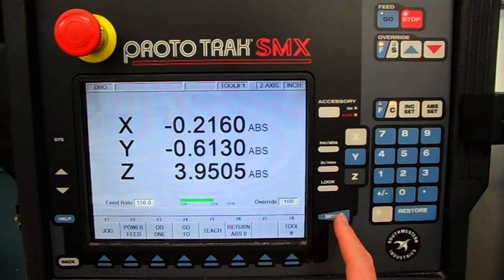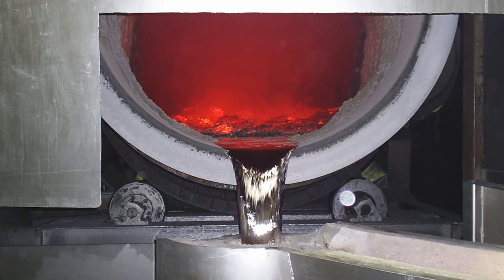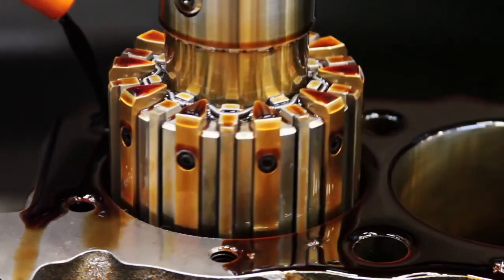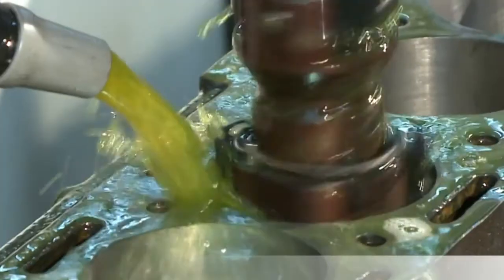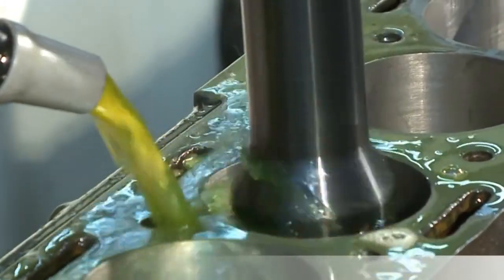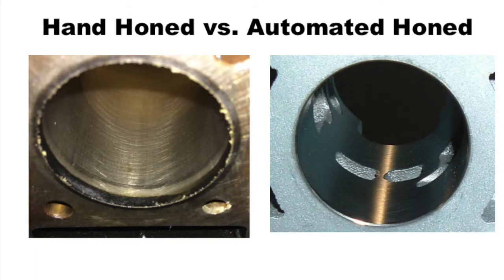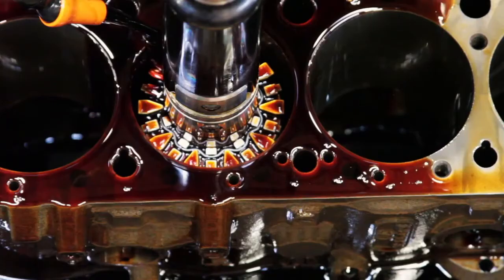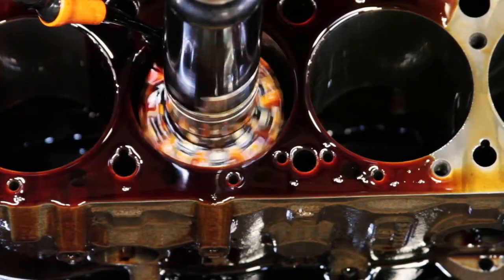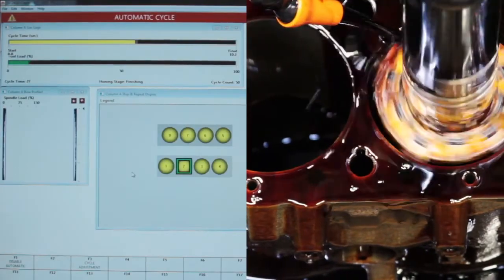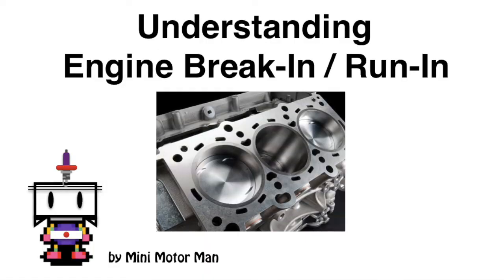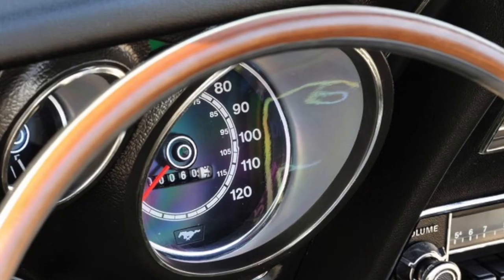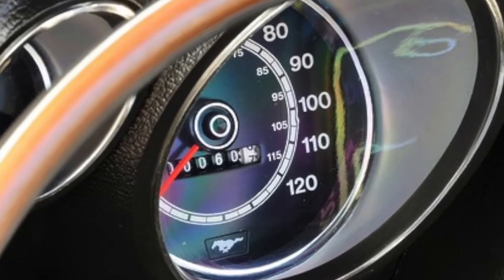However, as technology increased in precision, materials advanced in consistency, and manufacturing efficiency increased along with it, parts could not only be made with greater speed, but also with a tighter degree of consistency, meaning that now an engine's cylinders can be created with a very narrow margin of variation in the roughness of the cylinder. Not only can the machines create these surfaces, but machines can accurately verify these easily as well, and it is because of this that engines can be broken in a remarkably short period of time compared to before, sometimes in as little as 60 miles.